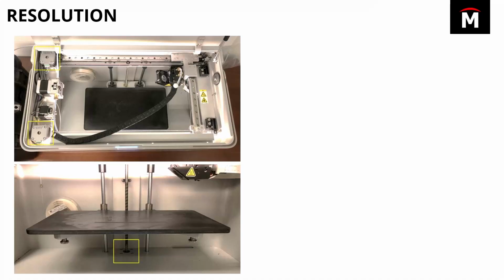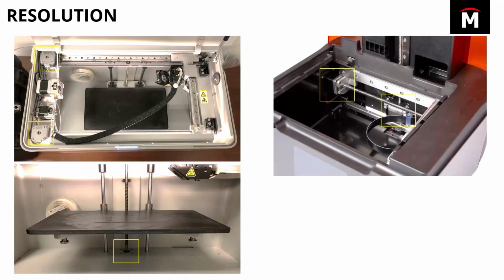And similarly, right, we've got that third axis we talked about, that Z-axis. We have a motor that's controlling the movement of that print bed up and down. Now, with an SLA printer, we also have stepper motors. We have a stepper motor that moves that light processing unit across the X-axis. That's that horizontal lead screw we see there. There's motors inside the LPU that move the laser in the Y-axis. And then there's a stepper motor that moves that bed up and down on the Z-axis.